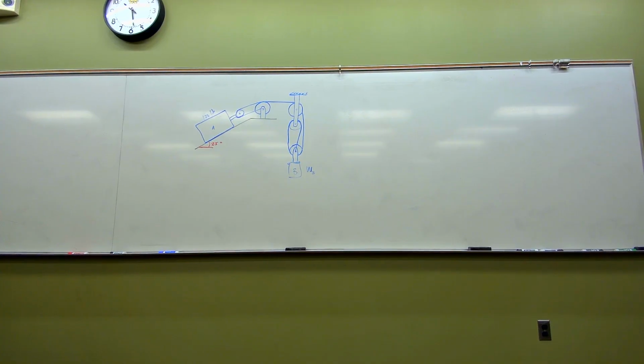The second, and I think by far the most important takeaway, is the thing we need to make sure we get down. If we really buy into this, then friction's an absolute nothing burger. And that is that the directionality of the frictional forces must always oppose impending motion. If you do that part right, the rest of this is pretty straightforward.